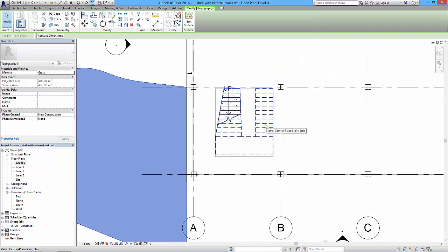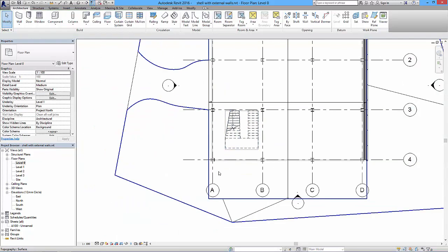I've been looking online at various different websites. The Revit Cat, for example, has got many different blog pages which explain the whys and wherefores and the do's and don'ts for creating sketch-based stairs these days. They are very flexible when you create a sketch-based stair, but they don't tend to behave the way they used to. So hence my confusion in class on that. So that's a method by which you can make a non-standard type of run, and it works with the landing and other elements of the stairs as well, but just be careful with the way you treat it.